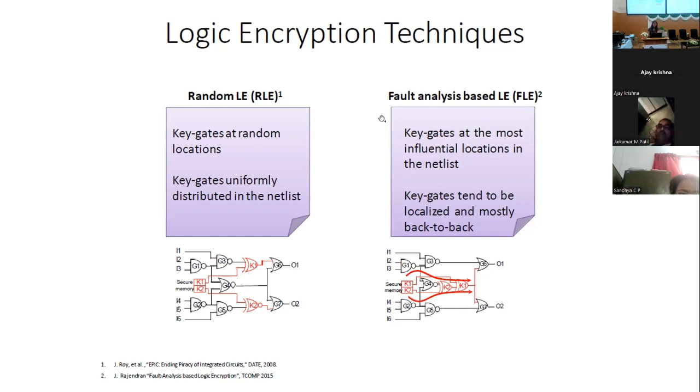Fault analysis means if I am inserting some additional gates inside my circuit, how much fault it is giving to the output. Based on that, I will insert my key gates. The position and the number of key gates will be decided by how much fault it is producing in the output with the wrong key.